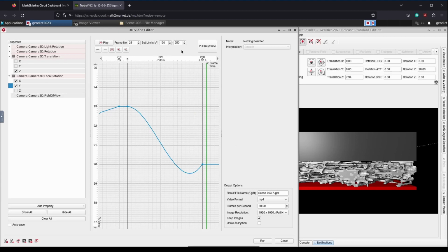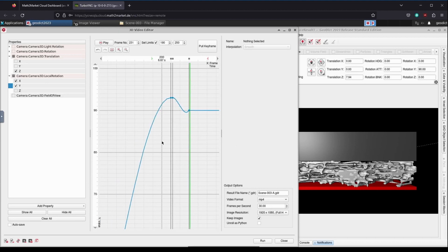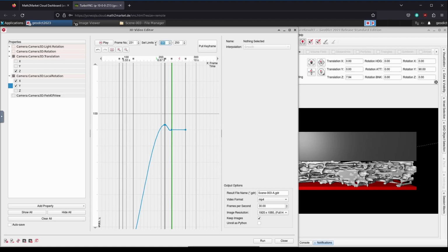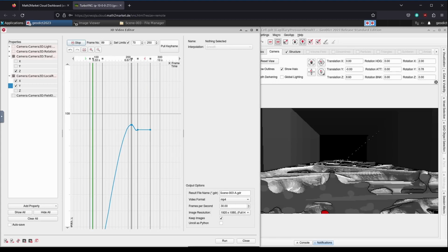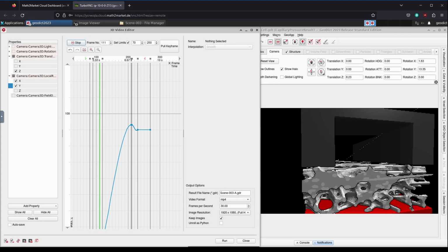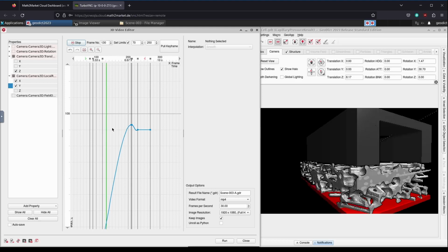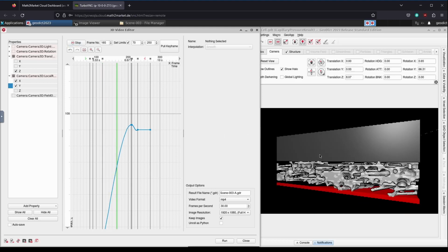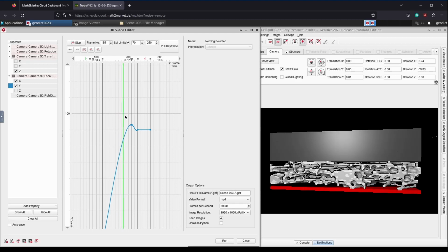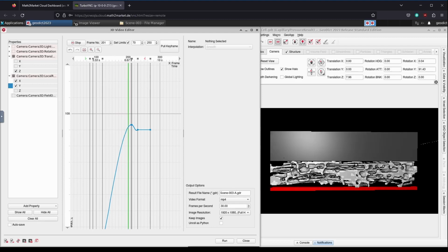We briefly check the set limit settings so that we see the entire animation from frame 70 to frame 250. Then we play the animation. Finally, we let the camera tilt a bit as soon as the rotation starts to give a feeling of inertia and centrifugal forces. Before we do that, we will stop the playback and save.